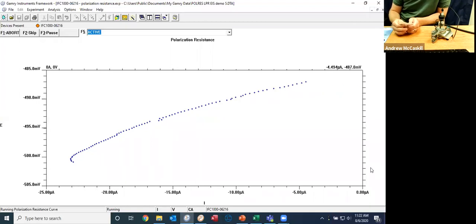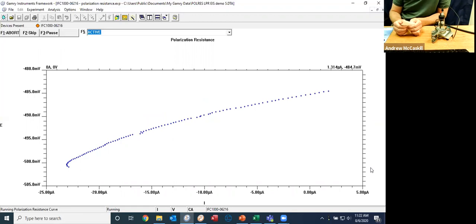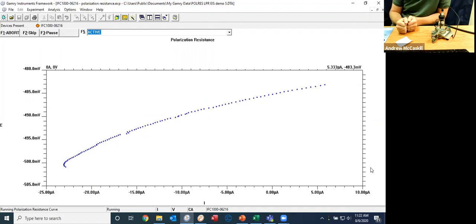The other thing is that the O-ring, that curvature, as it meets your sample, can kind of skew what your results are going to be. You can have something called edge effects. So by using the sample mask, you avoid that curvature of the circular O-ring meeting the flat surface and that crevice that's formed right there. So that's another big reason to use the sample mask.